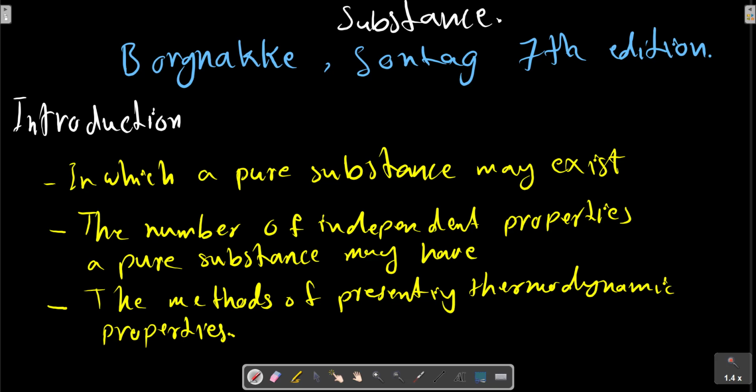We must size equipment such as the boiler or heat exchanger, turbine, and pumps for the desired transfer of energy and flow of water. As the water is transferred from liquid to vapor, we need to know the temperature for a given pressure, and we must know the density or specific volume so that the piping can be properly dimensioned for the flow. If the pipes are too small, for example, the expansion creates excessive velocity, leading to pressure losses and increased friction, thus demanding a larger pump and reducing the turbine's work output.